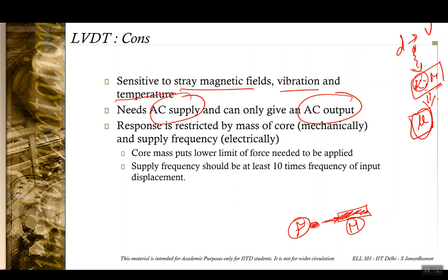If the force causing the displacement is very small, then you need a very sensitive LVDT whose core has much less mass.